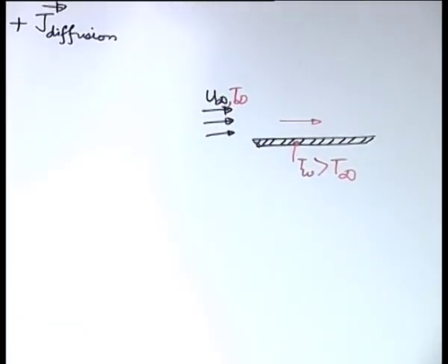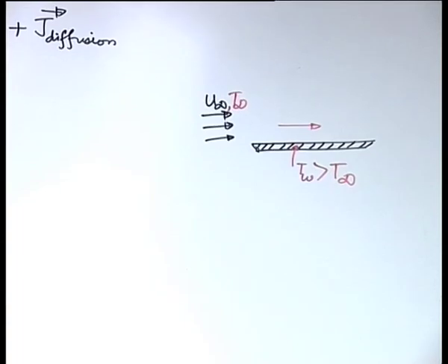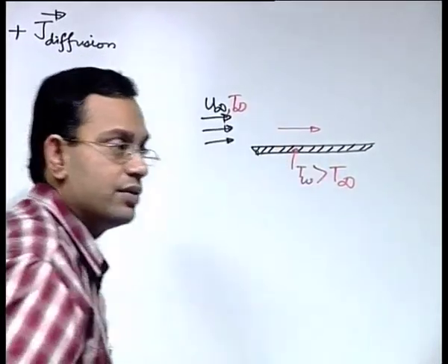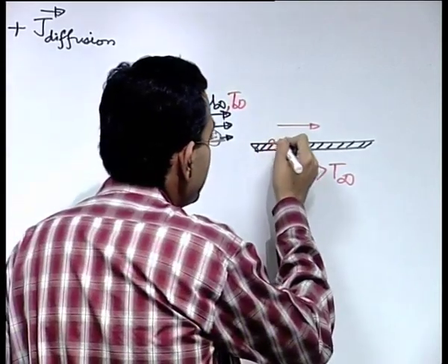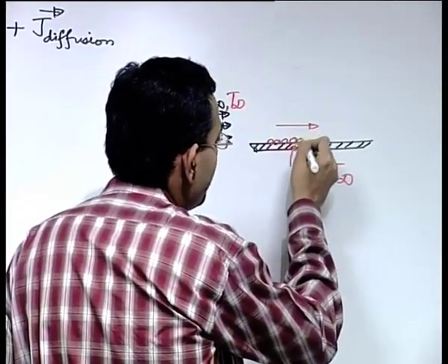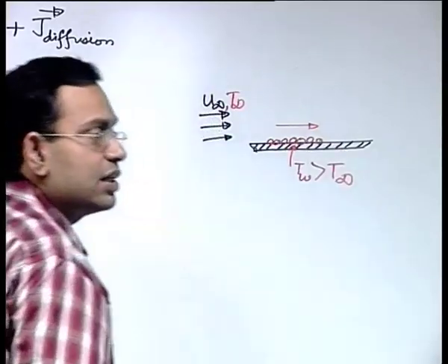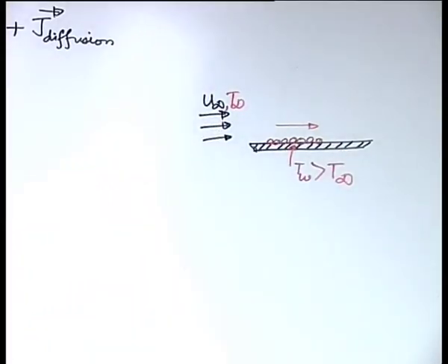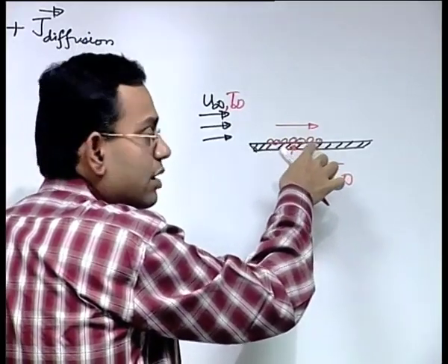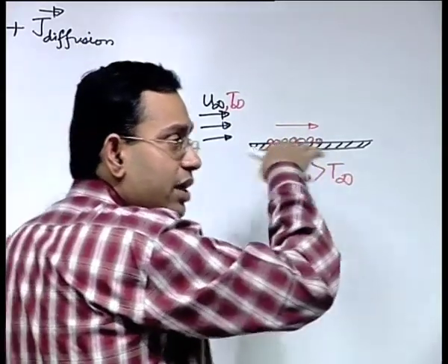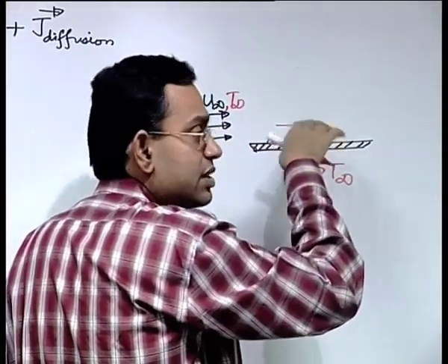But the first question that we have to answer is, how does the heat reach the fluid? Of course, consider the fluid adhering to the solid boundary, this is stationary by the no slip boundary condition, until and unless there are special circumstances when the boundary condition is violated. In the general case it is a no slip boundary condition. So, under that condition, here you have stationary molecules, on an average the fluid layer is fixed.